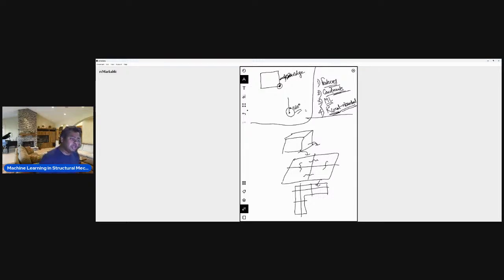So in the next lecture, what we will talk about is, we talked about the unassembled element, single element, and how we can reproduce different aspects of it, such as stiffness matrix, quality of displacement results, quality of eigenvalues, and things like that. But going forward, we would also demonstrate, maybe in terms of crystal plasticity, how the eigenvalues deviate from their elastic counterpart, and whether that could be captured or not.